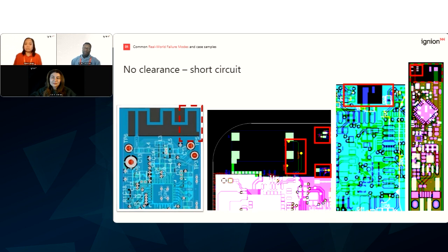So yeah, we get it. Sometimes, our typical customers will say, well, I didn't have enough space. Or some of the designs are an afterthought. It could be something like an LED that needs to light up. And an obvious place to place it is in that keep out area. But those LED leads do have some traces, copper, essentially influencing performance, right? So these are things to look out for.